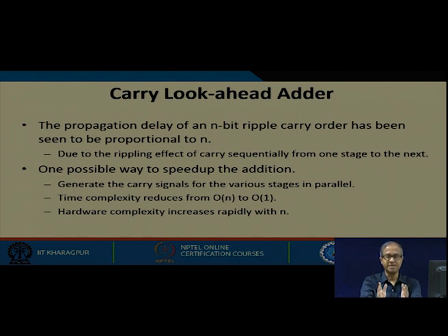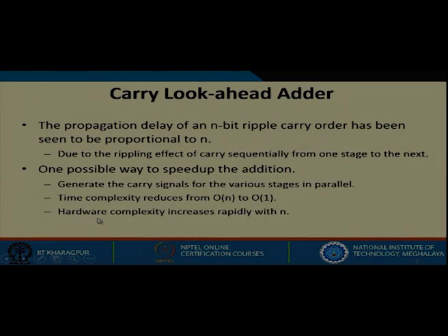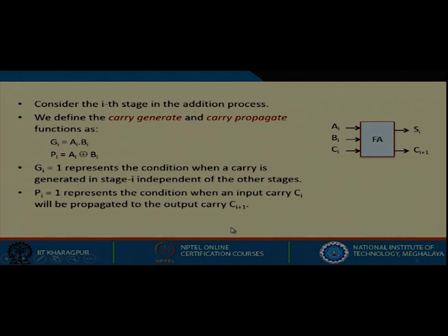If you can do that, then all the full adders can carry out their additions simultaneously. They need not wait for the previous full adder to complete. This is the basic idea behind the carry look ahead adder. But the only trouble here is that the hardware complexity, the amount of gates that will be required, will increase rapidly with n. This is the drawback of the carry look ahead adder. So, let us see the basic idea.